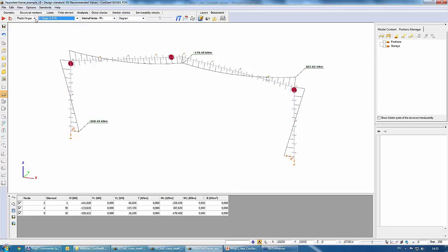And we can see the deformation and the internal force diagram at any stage of our plastic analysis. And in the first order analysis, that means that for load level 1, so at the design load level, a special analysis is performed, in which all the plastic hinges which formed before the design load level are considered. Now 2 plastic hinges are under 1, if we see the stages.